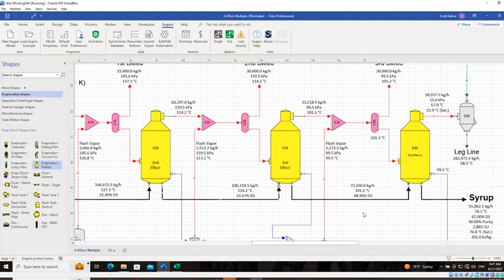So if you're using a 3.9 model, you can scrub it and use it in 4.4. But there is no way to go the other direction. So my suggestion would be to just save a backup, which the model scrubber actually saves automatically anytime you scrub a model. But once you've saved a model in 4.4, it will only be usable in 4.4 or later versions.